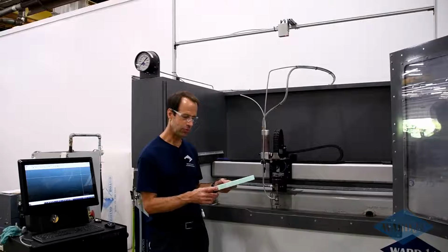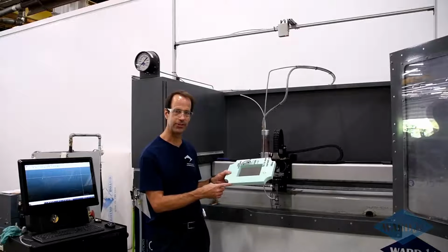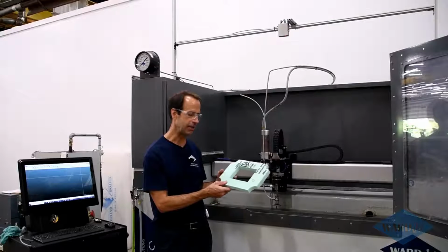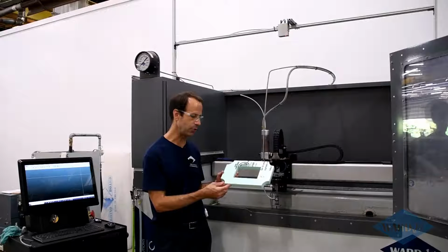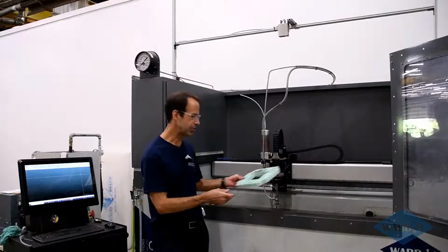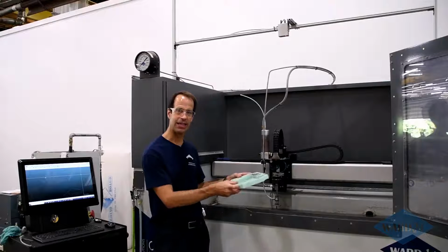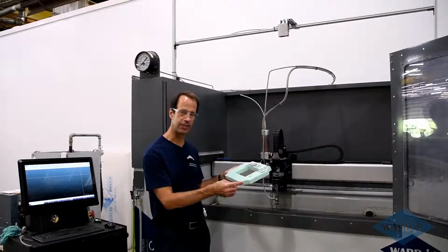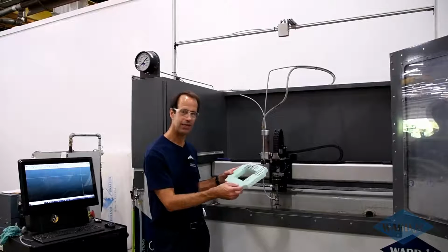So one little tip on a part like this where we do have a nice straight edge to make my life a little bit easier when I get to the CAD work: if I cut myself a straight edge here that I can butt this up against, then that'll make it nice and square when I bring it into IGEMS. So that's what I'll do here first, and then we'll lay this down and take a picture of it.